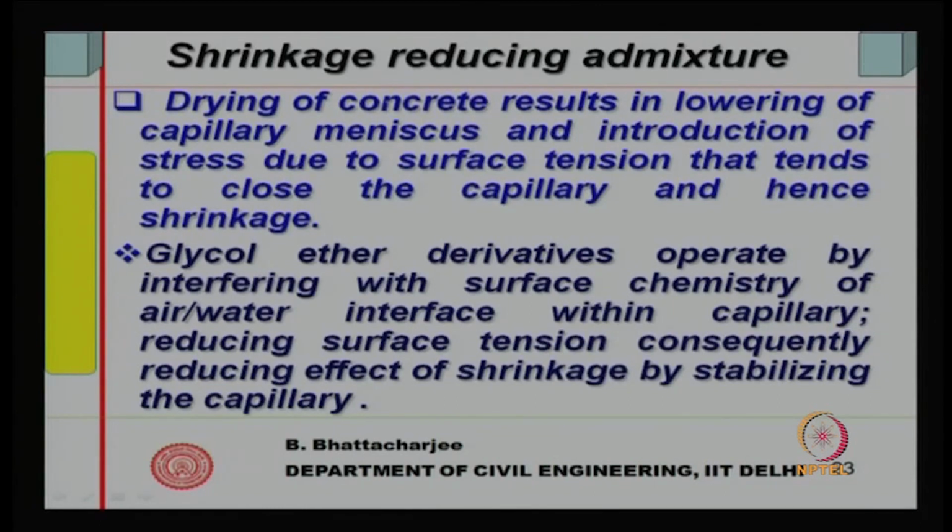Then of course, gel pores will also become empty. The water will move out from the gel pores subsequently, so there is shrinkage of the paste and hence the concrete.